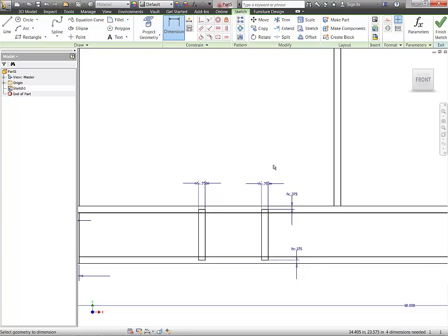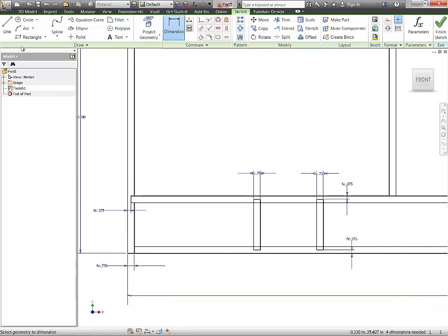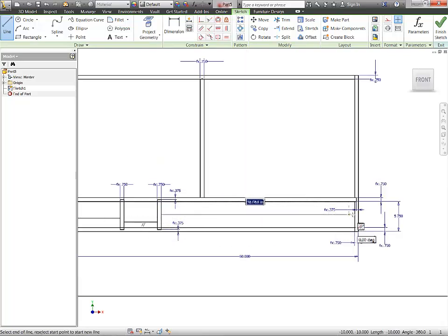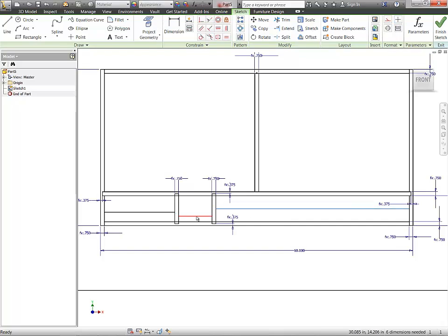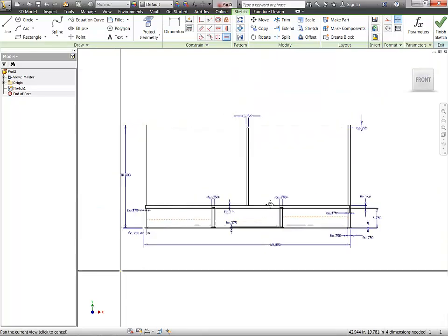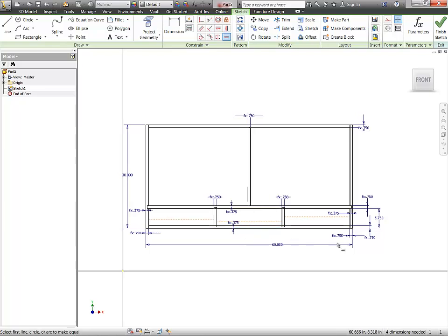Now, I want them centered. I want to center it in the bottom, thusly that no matter how wide the cabinet becomes, these will always be centered. Three separate openings. So I just draw some simple lines. I'm going to highlight each line. I'm going to go up to the top and say it's a construction line and also make them equal, and immediately what just happens is that it now has equal opening and I don't have to calculate anything.